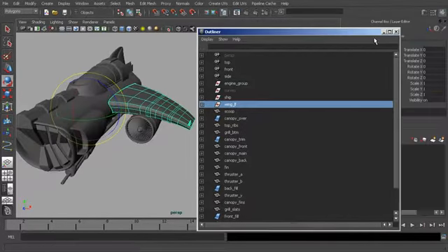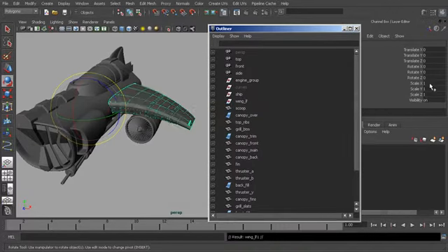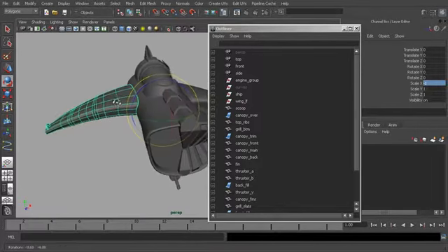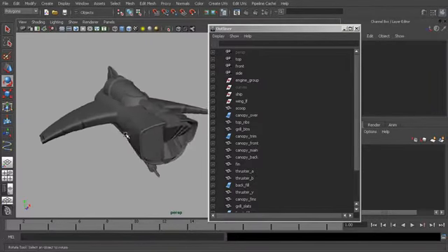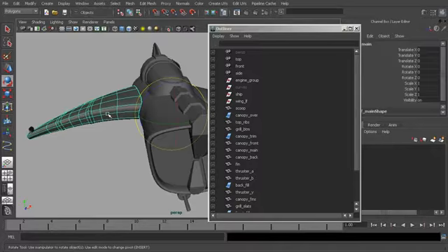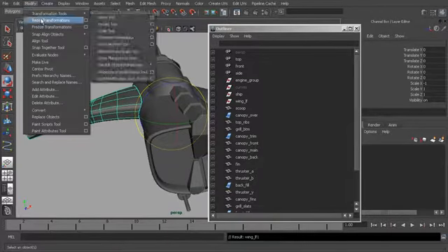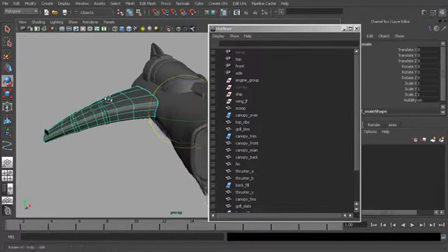One of the tricks that people will often do is to take this geometry, go ahead and duplicate it, and then scale it negatively across the axis. So setting that scale in the x to -1, it has essentially flipped it across the axis. So you can see we get the symmetrical wing over on the other side. Now one of the things to be aware of is that this group now has a negative transform on it, a negative scale. So if I were to go in now and freeze the transformations, it is going to try to compensate for that by reversing some of the things associated with this.